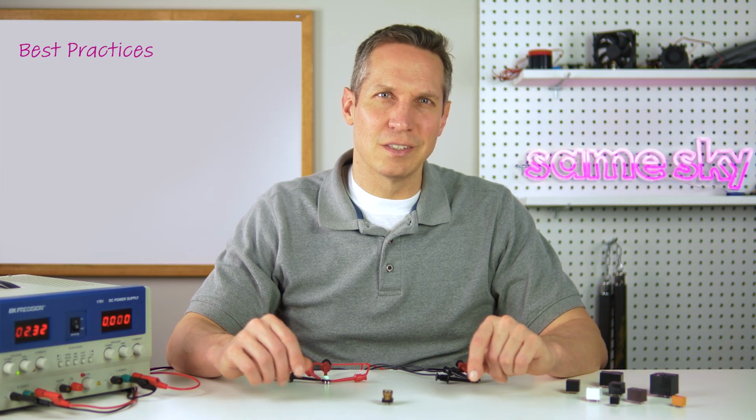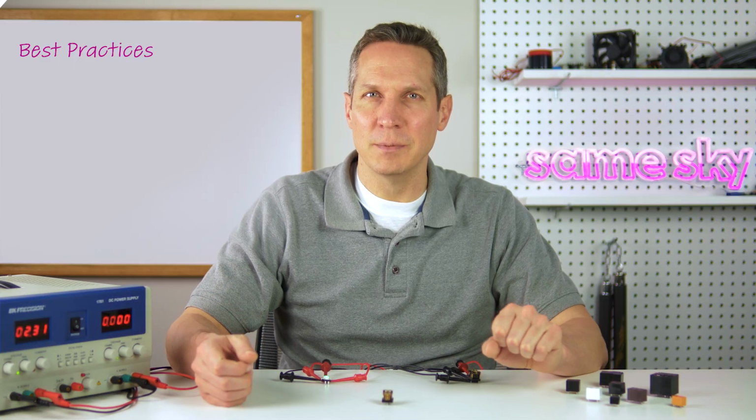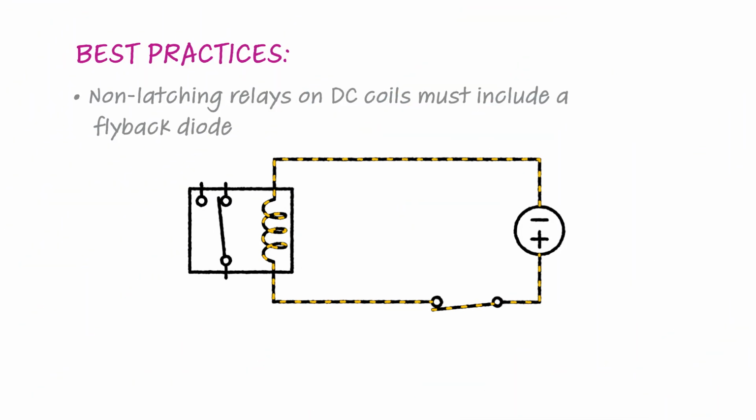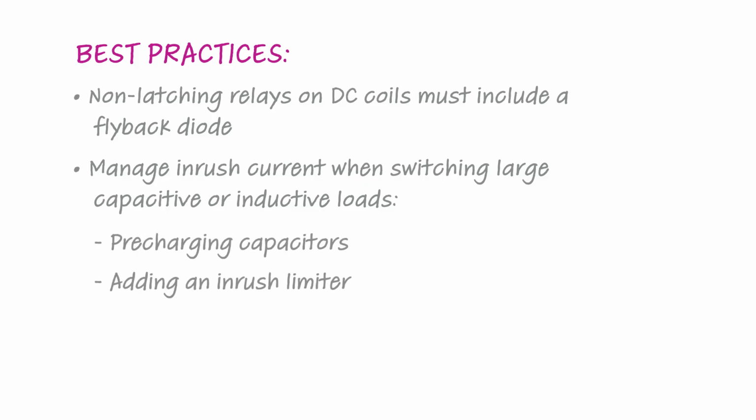When working with relays, there are several best practices that we recommend to improve performance and reliability. When working with non-latching relays on DC coils, always include a flyback diode to prevent voltage spikes. For both relay types, you should manage inrush current if you are switching large capacitive or inductive loads. Pre-charging capacitors or adding an inrush limiter can prevent large current spikes that would otherwise stress the contacts.